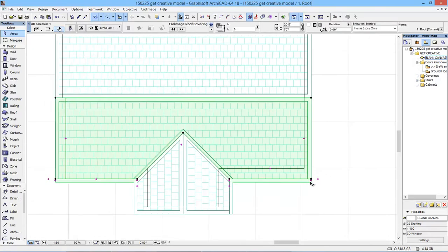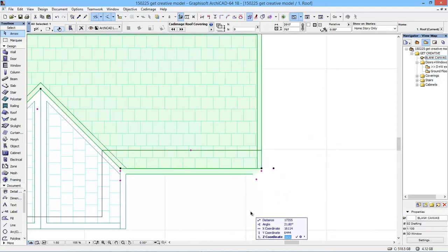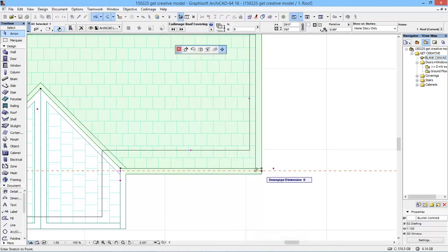We are going to have one over here, and the way we put it down is we select the covering, and you'll see there's a couple of hotspots that are intelligent, like the coloured ones. The first one allows us to choose a custom angle. So if you were manually combining two different bits of buildings with coverings, then you could go and set that. But this is the one I'm after, because this creates the downpipe.